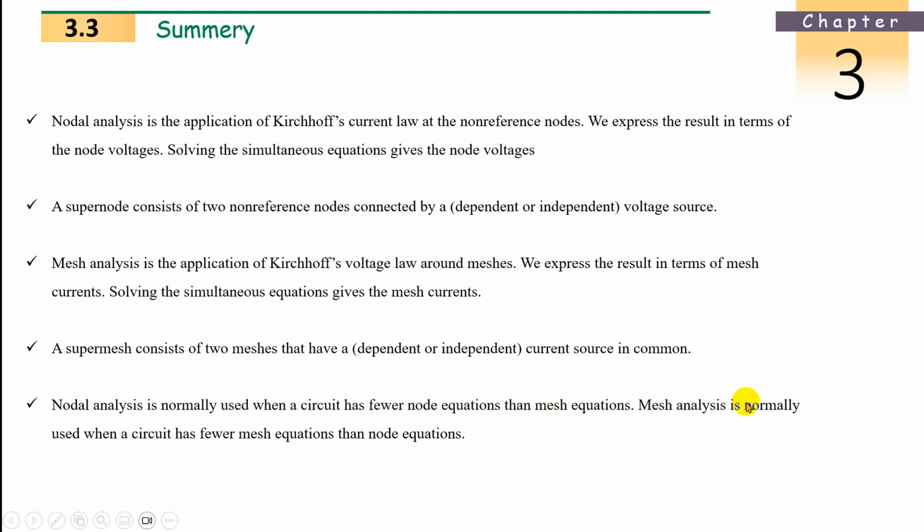Mesh analysis is normally used when the circuit has fewer mesh equations, which is less, you can use that one. If you have two mesh equations and mesh loops and 4 nodes, which one is better? Mesh. If you have more nodes, fewer loops, then which one is better? Nodes.